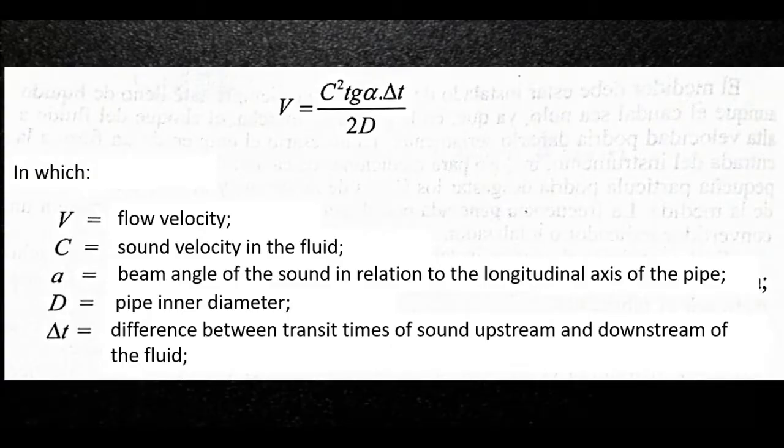The receiving crystal is exposed to these pressure fluctuations and responds by vibrating as well. This vibration produces an electrical signal proportional to the displacement of the piezoelectric transducer. The sensors are located inside a pipe whose area and velocity profile are known. The principles of operation are very varied. In one of the simplest models, the speed of the fluid is determined with this formula.